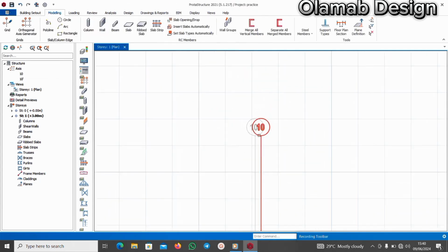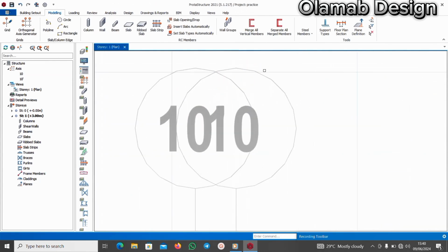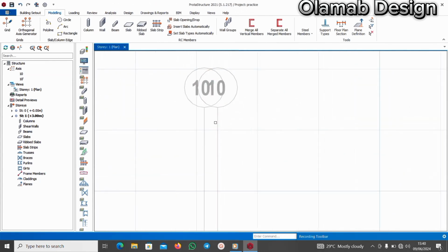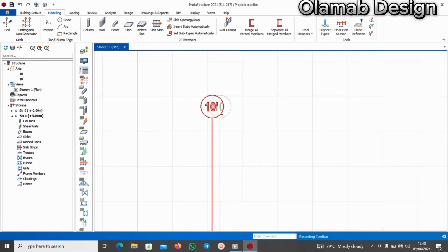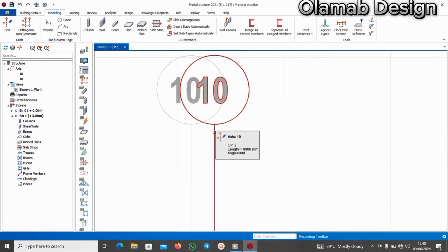This is according to what the architect has provided before, because you must not touch the architectural grid. If you want to have your own structural grid, maybe you felt it's important for you to have some other grid, then you can create your own grid and give it another label, but similar to the label the architect has given to the drawing.